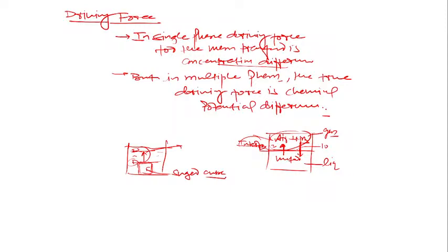So as time progresses, if you keep this mixture for sufficient time at the given temperature and pressure, then what happens? The concentration of ammonia in the water in the liquid phase will increase. Yes or no? Previously the water was pure, but when you allow it to be in contact with the air-ammonia mixture, the ammonia will get dissolved into the water, and that is why the concentration of ammonia in the liquid phase will increase, and it will keep changing till equilibrium is established.